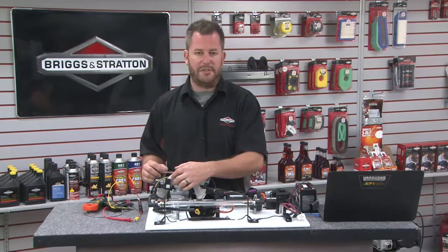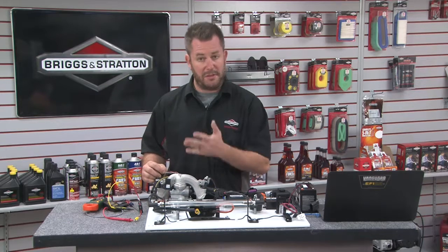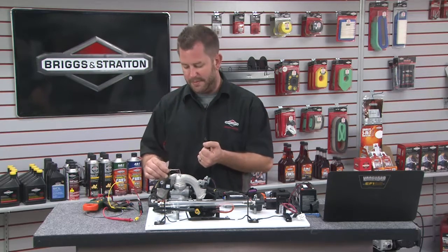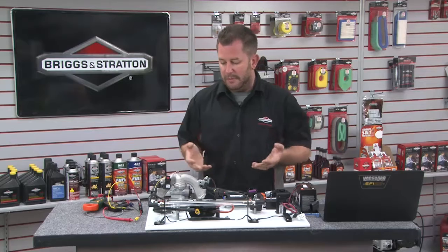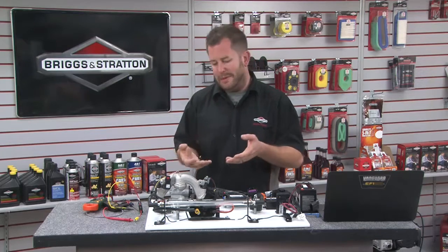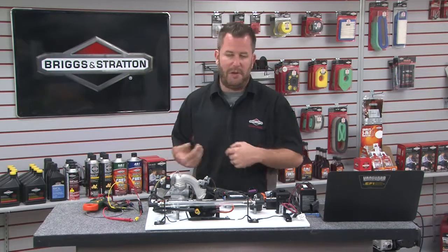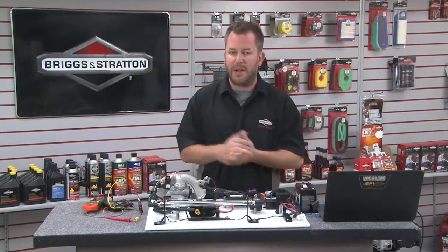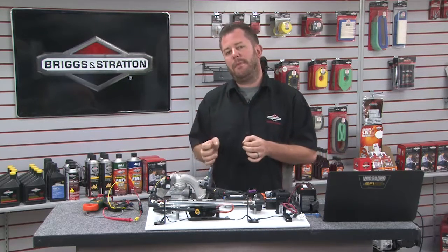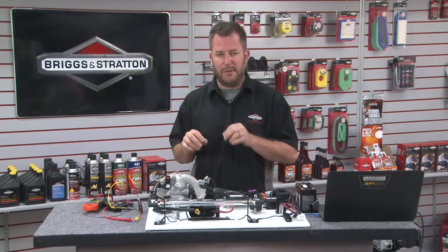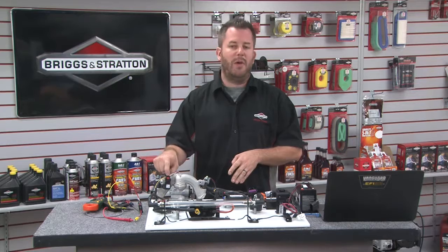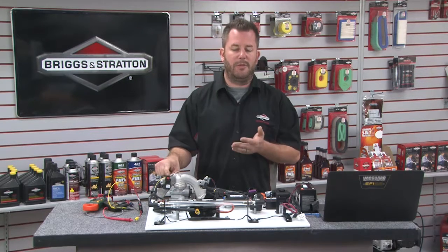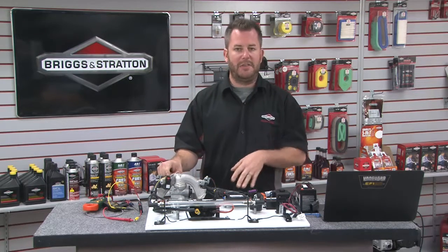Okay. Also, you want to verify your map sensor pins, make sure they're all there. Everything looks okay with this one. So I'll go ahead and reconnect it again. All right. So at this point, what we would end up doing here is really just replacing the map sensor because we did a scientific test here. We basically proved everything else but the sensor seems to be working correctly. Now the default operation of this is when the engine goes into what they call limp mode here, or a default operation, when we can't rely on this sensor to give us an accurate temperature input, it just defaults to the engine head temperature.